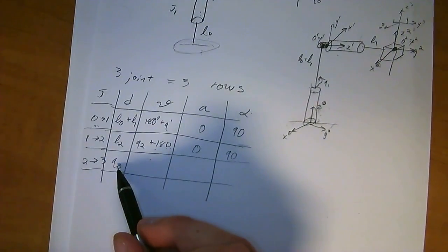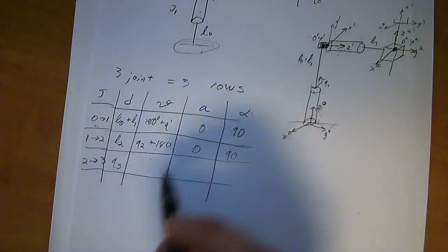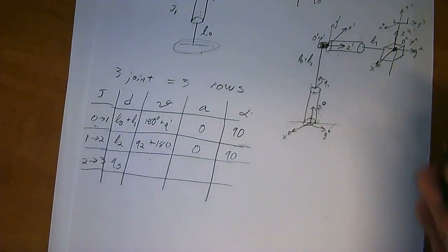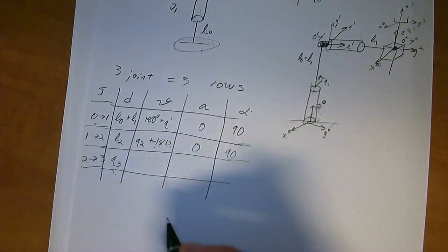And with transverse directions, you always want to detail Q3 in the direction that's positive with respect to that axis. So like right here, we're moving positive in the entire axis system, so it's a positive Q3. You don't consider any kind of a length down here, or the fact that it can move this direction. Only the approaching direction will define what is positive and what is negative.